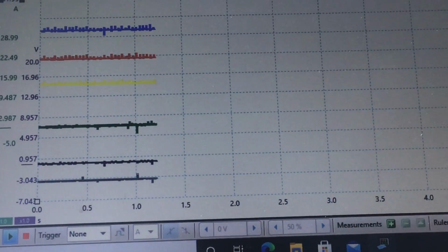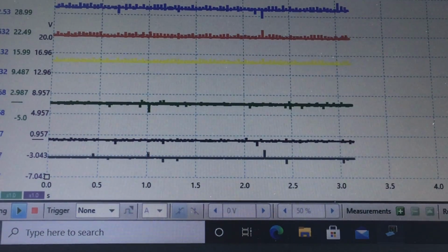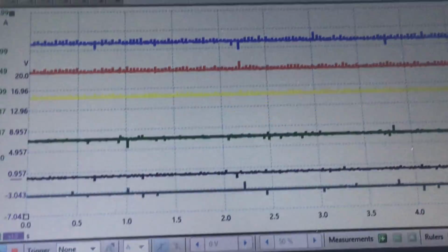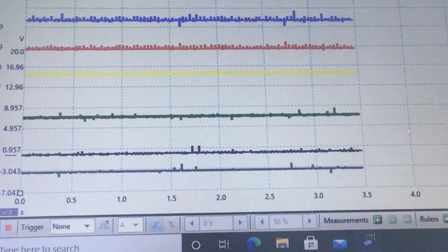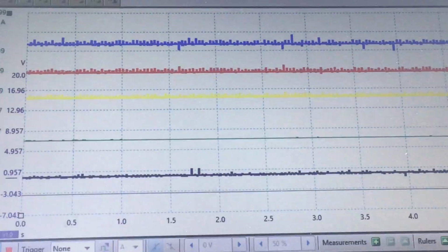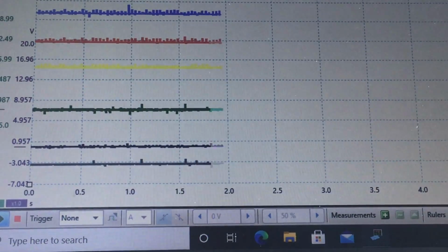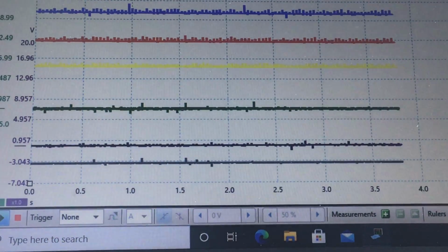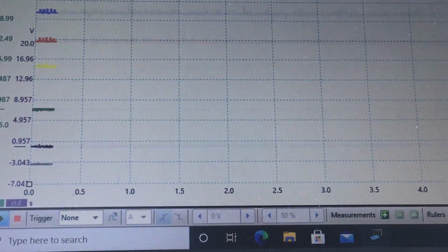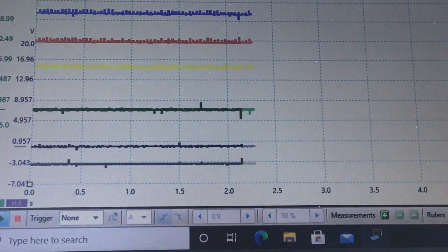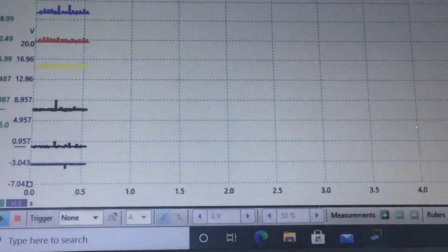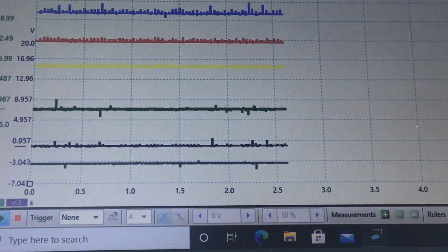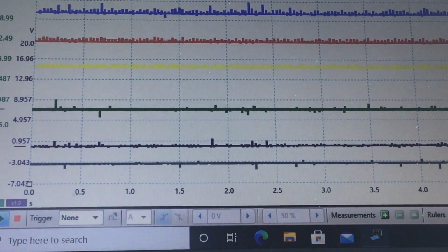By the way, if you haven't taken a snapshot of the schematic, please do. Just roll it back to the time I was showing the schematic. It'll make it easier to understand the scope captures. Channel red is on the ground side right at the blower motor, and basically that's going to mirror channel blue, which is at the feed side, because there is no ground. It's kind of deadheading through the motor, and the voltages are equal.